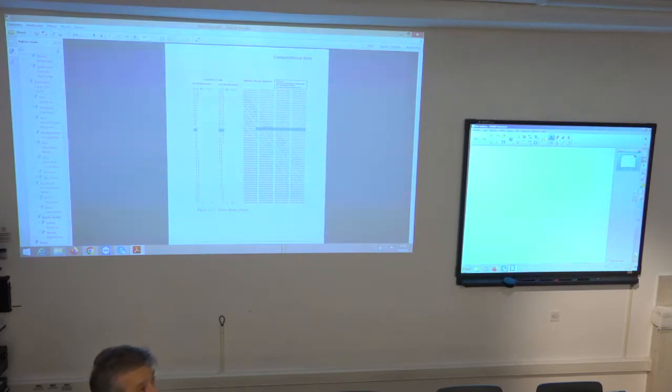The idea is that such huge dynamics of shifting doesn't make much sense, but it solves exceptions. So normally you would have this range plus minus 32 bit positions. But if, for example, based on some computation, it turns out that you have to shift 50 positions, then it's not a problem.